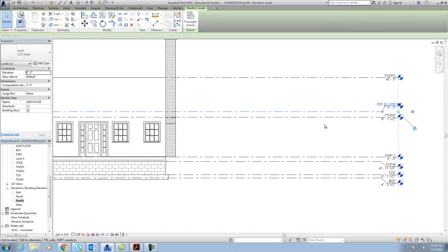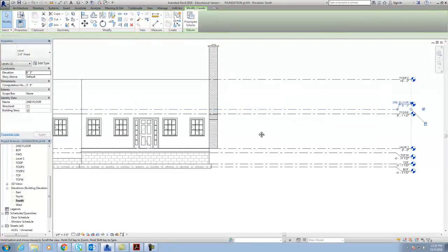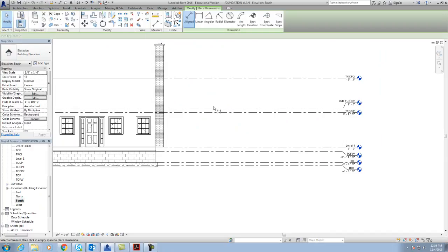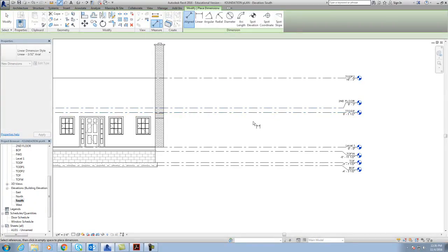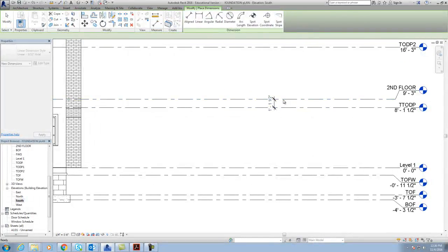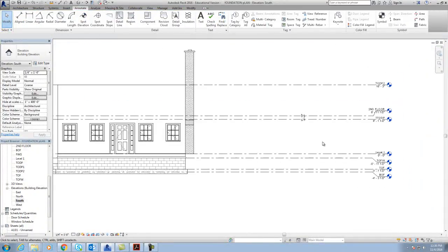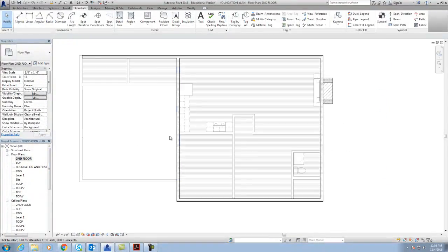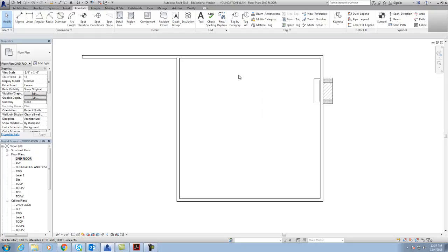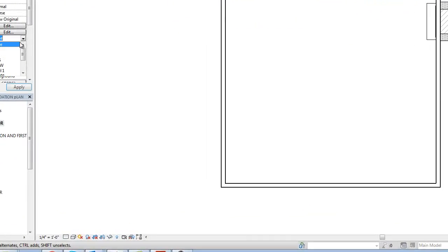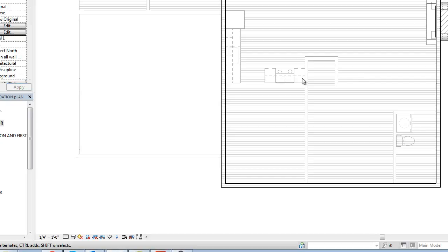So click on this, and if you don't see a measurement, you can hit annotate and align and go between them and click. And then click on this line here, and this one would be 10 inches. This is your second floor. And now when I go back to second floor, see how it's showing my exterior walls? Even if I turn my underlay off, it's still showing my exterior walls. But I want my underlay on so I can know exactly of level 1. That way I know exactly where this load-bearing wall is so I can build this.